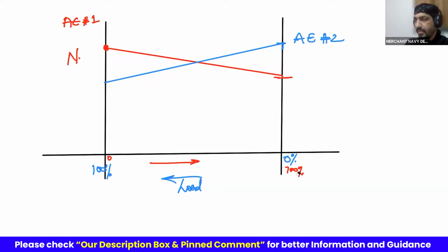Okay, so this is slightly swept. We'll just draw again, 0% load and then 100%. The point of intersection decides actually the load sharing that they will be having. First of all, droop is basically the percentage drop in the RPM when the load is changed from 0 to 100. So how much percentage of the RPM will be dropping?